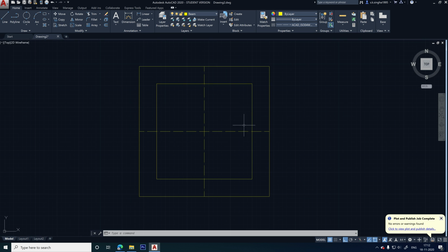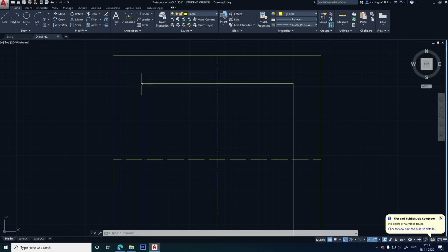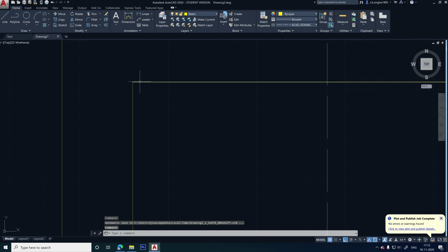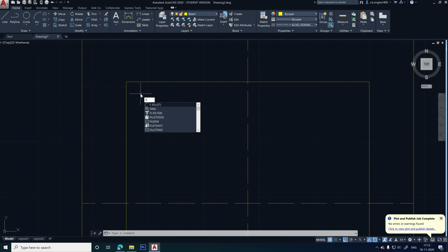I don't know here the array can be, let us check. Okay, before that you make the fillet, because the rebars are not physically like a 90-degree angle. Okay, so the diameter of the bar which are placed over here, the longitudinal reinforcement bar, basically they are having the diameter of 25 millimeter. So let us make a fillet.